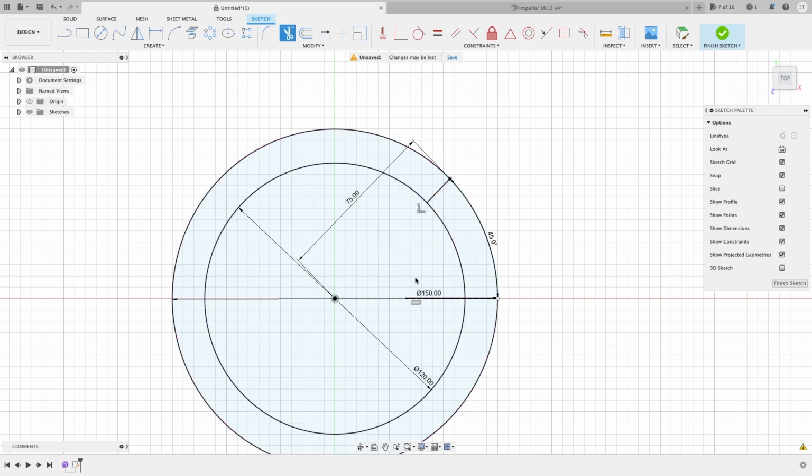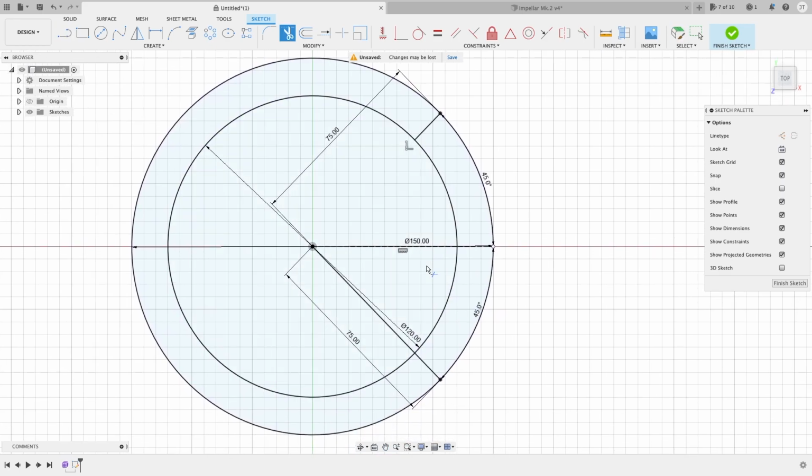Now let's say we want to make another angle here, and we want to make a 45 here. So we hit tab, we go 75 to keep our tab there, and we want to go to a 45 degree angle here. We would do the same thing, and we would hit our T for our trim tool. We could then get rid of that line.